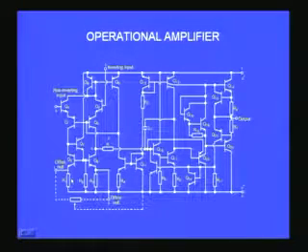And if you look at the resistors, you will find there are only up to R11. So you have only about 11 resistors, 20 transistors. You have more transistors than resistors. And do you have any capacitors? Yes, you have only one capacitor at the center, which is actually a compensating capacitor, for frequency compensation. So you have 20 transistors, about 11 resistors, and one capacitor. This is in striking contrast to what you normally come across in discrete electronics. In discrete electronics, you would find very few active devices, and a larger number of passive devices like resistors and capacitors.